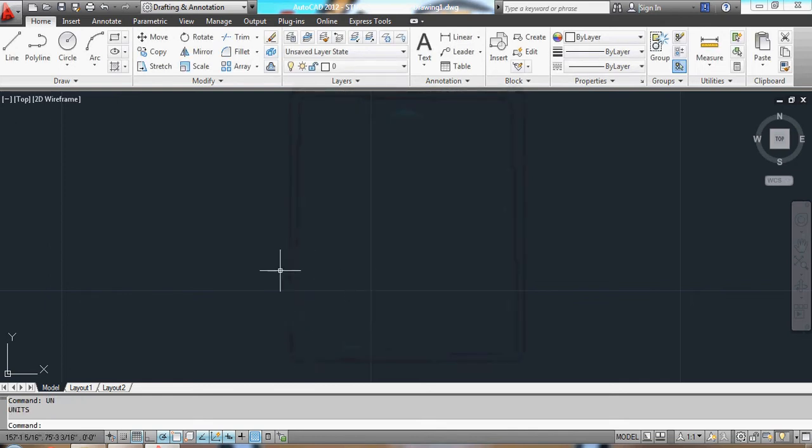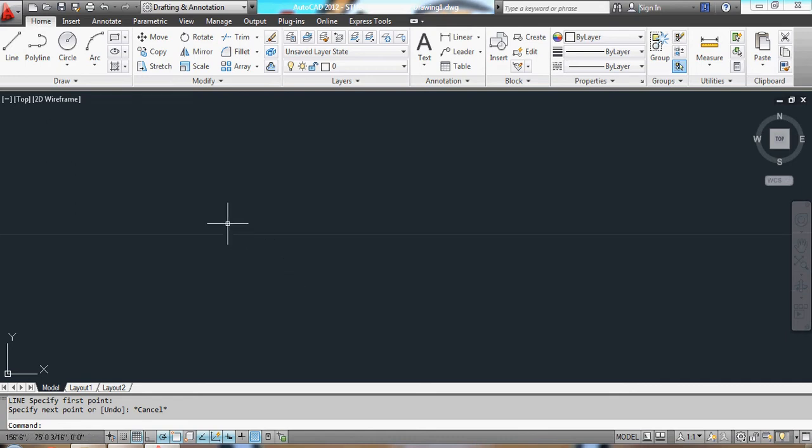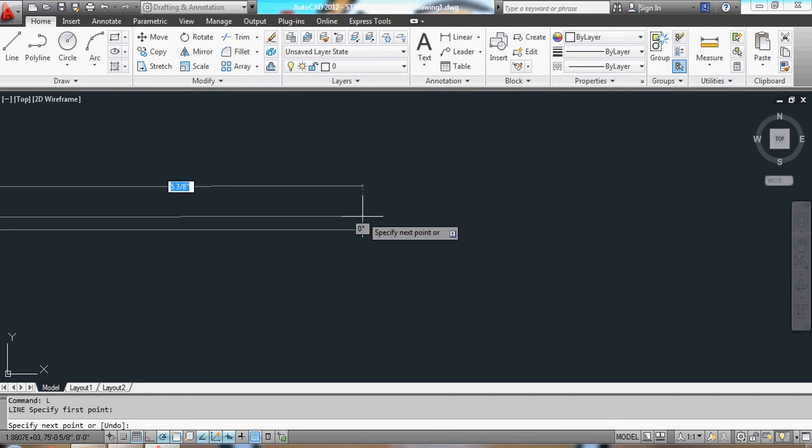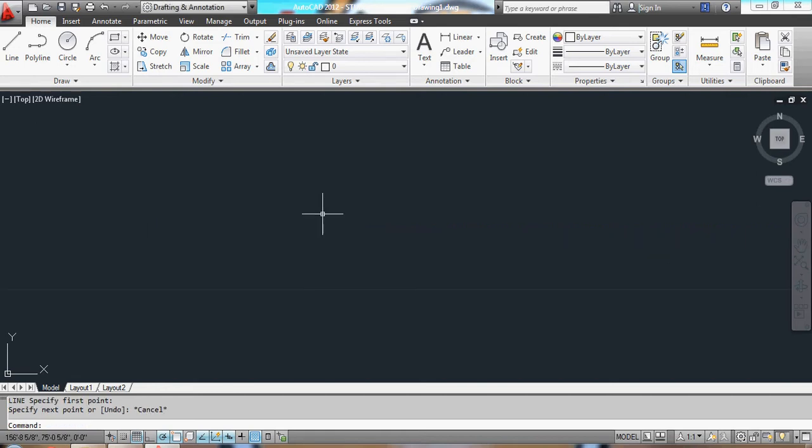Same idea, good practice. So I'm just going to start by saying that the click and drag method to drawing a line like this isn't quite accurate, and I'll show you that here. So I'll zoom in. L space click drag, and hold on, I'll zoom in a little bit more. See here how there's kind of a good buffer room. See how it's staying at 5 foot 3/8 of an inch, and you've got all this wiggle room. So that just shows that your measurements are going to be slightly off when you use the click and drag method and trust the measurements that come up on the screen.